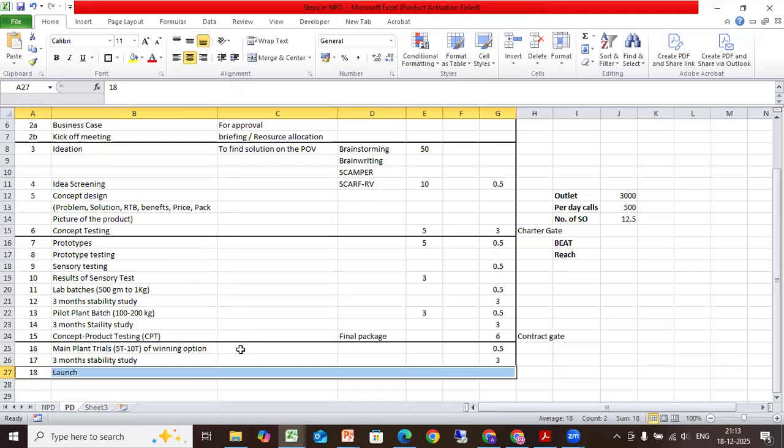Right. In gulab jamun, we use 2 ribbon blenders. One is to heat the maida at 60 to 70 degrees to remove the moisture and increase shelf life, which is the roaster. Then I take it to the second ribbon blender where I cool it and add other ingredients to it, and then take it via a screw conveyor to my filling hopper. Okay.